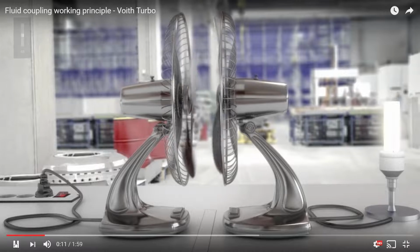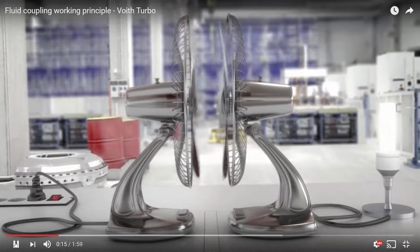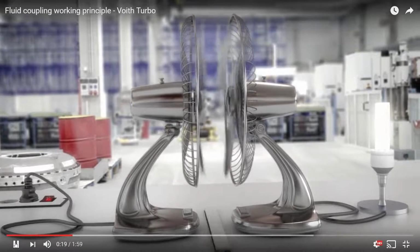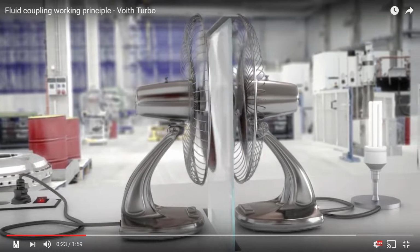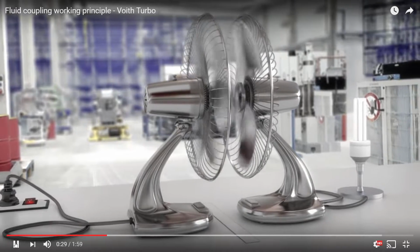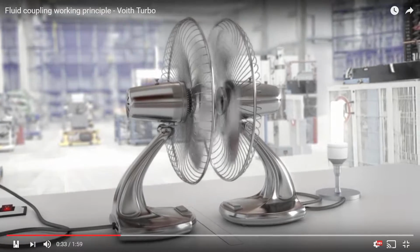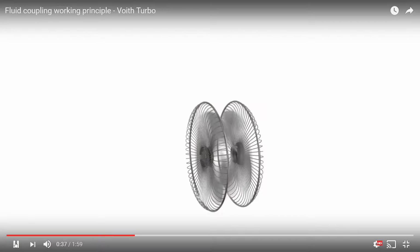So you can see that first fan is spinning. It's actually forcing the other fan to spin. Same thing happens inside a torque converter. You have two turbines that spin right next to each other. The difference is there's fluid in between the two. So you can see the first fan spinning, even though it's not touching the second fan, it's causing it to spin.